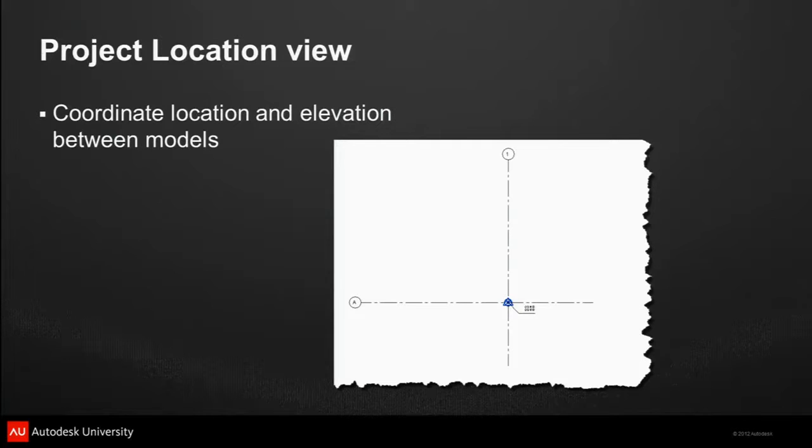The grids are in here. This is a clip from about 1.5 years ago, actually, that I have. Don't have grids in your project if you're doing analytical import and export. Learn it the hard way, right? Import an analytical view, and it's got grid 1 and grid A already in there. It starts naming after that, hey? 2, 3, 4, 5. Doesn't match.